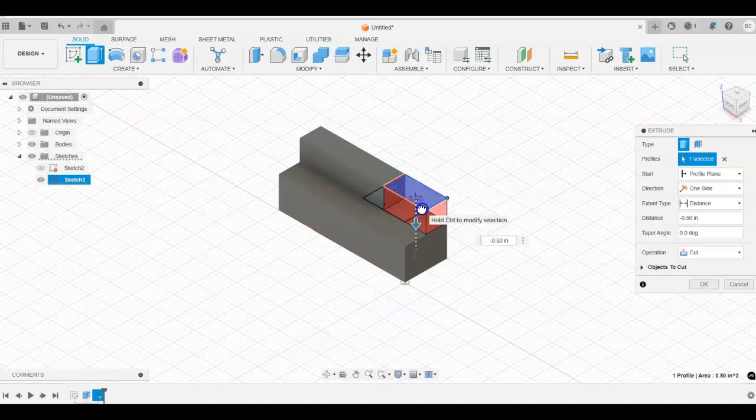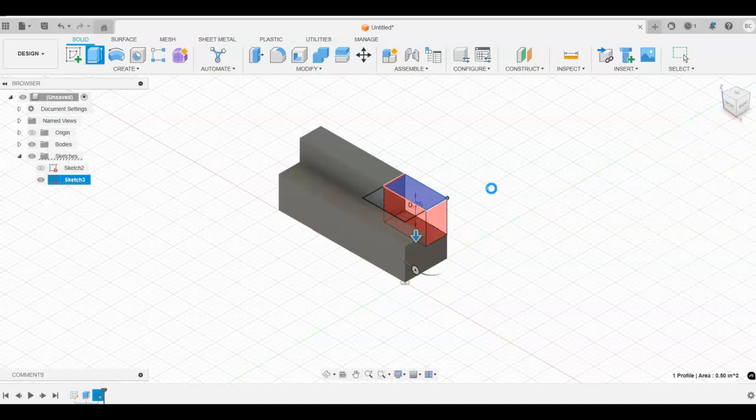In this case, we're cutting it, and we see that dimension, so we've got to create a dimensional constraint here too, or we can sit here and look at the print and do the math. Well, the math says that we're taking the 1¼ inch overall height of the part, and this shoulder is only a ½ inch up. So I can take 1¼ minus the 0.5 or ½ inch, and that means we know we're going to be minus 0.75 here to go down. All right, so I just hit enter.